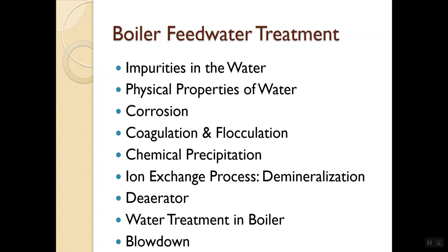And the last line here is blowdown. Blowdown is removing water from the boiler system. We talked about this back in equipment class as well. As we have that water cycling through the boiler, it's still going to pick up some corrosion. It's still going to have some solids that get through the system, not entirely pure. All of this doesn't work 100%, so we never have pure, clean, 100% water.